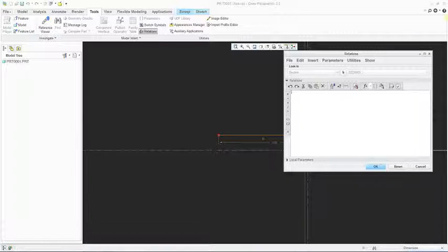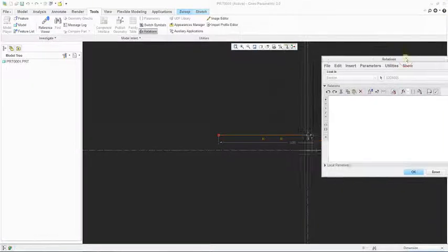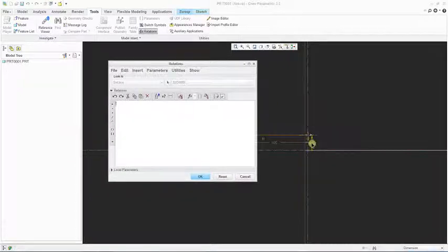Oh sorry, I need to select the, sorry about that. I forget sometimes. I'm absent-minded in this place. Select, sorry, let me add an equation which is equal to, I'm going to use sine in this place. Sine function I'm going to add to the trajpar. So sine of trajpar into, same equation again, 360 into, let's say 60, right? Now this time why am I giving 60? You can understand once you see the profile, what is going to happen in this place.